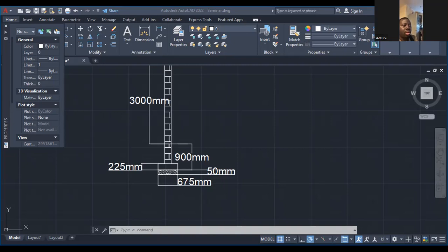It's volume. What you are doing in volume is you are displacing a space. The space you are displacing now is the excavated space you have already excavated. You are displacing it with concrete, which is mass concrete. The thickness of that concrete is 50 mm, while the length is going to run along all the walls, both the internal and external walls. That is why we are using our guards. And it's going to be between the faces of the excavation. That is why we are using our width of 675. Is it clear now? Okay.